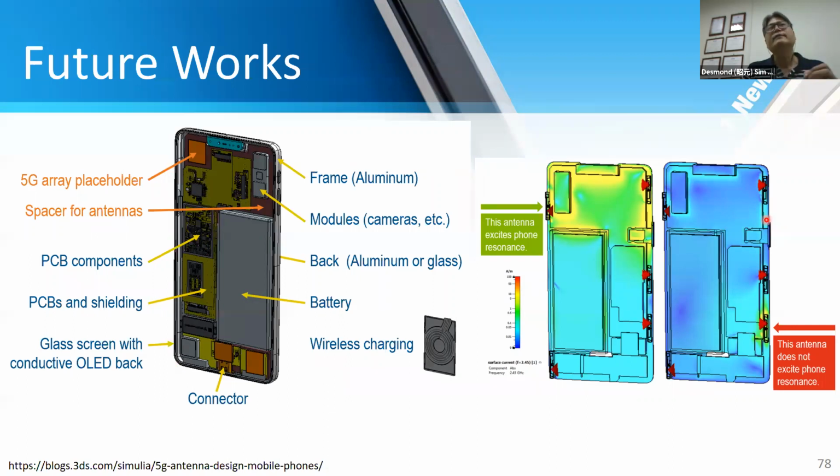And if you apply the characteristic mode into here, as you can see down here, the placing of the antenna is really, really important. Now you can see, if I try to excite somewhere around here, there's a large current distribution in here, meaning that because of the current distribution, you cannot place your antenna in this location.